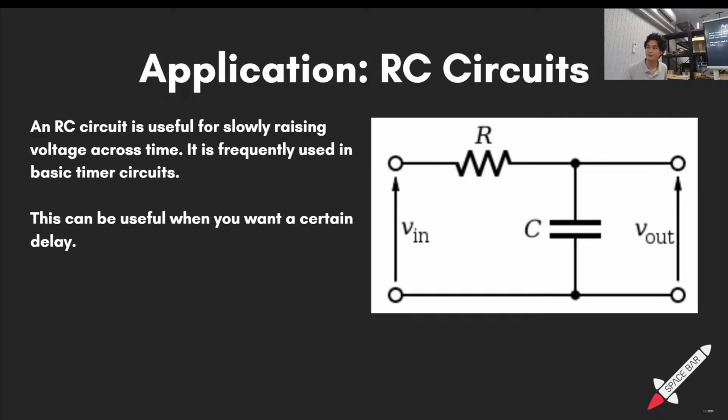Let's say there's 5 volts in, and then see the R, and what does it do at the right side? So if there's 5 volts in, is it... I'm just going to draw in blue now. So V in goes from 0 to 5 instantly, right? So this is 5. Or we assume it to be instant because this is our scope, right? Then this will be V in. Then your V out is going to look like this.